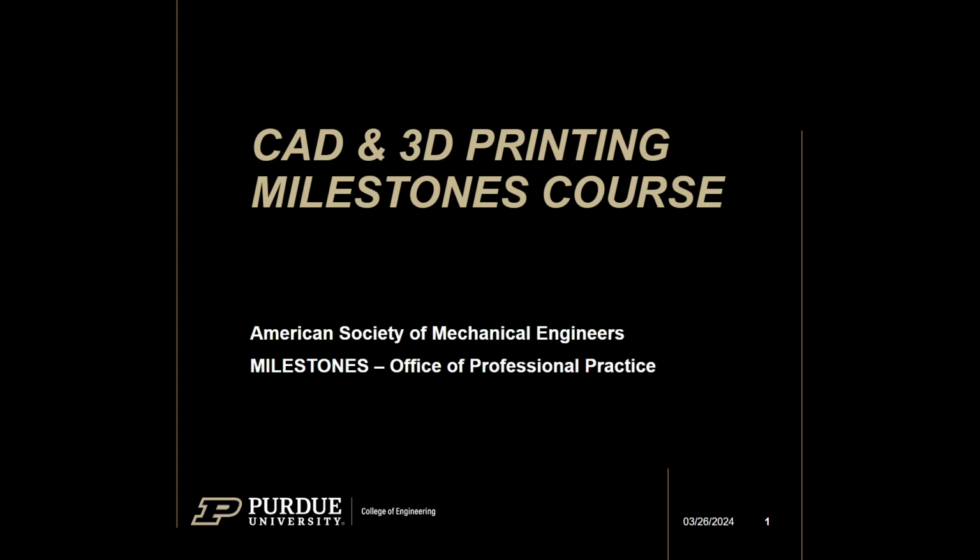To do that, last week we did a lot of dimensional tolerancing by using the sketch dimension tool to set lengths and distances relative to each other. But today we're going to be messing with geometric constraints, so using geometry to create your specified geometry. And then we're going to be teaching you a couple other tools to make more organic looking shapes.